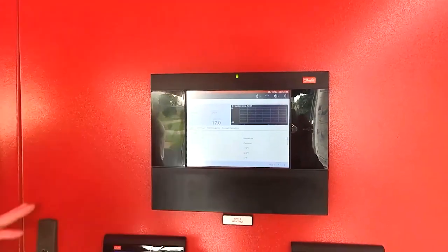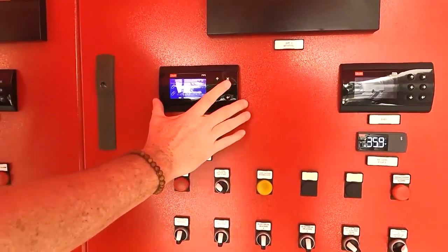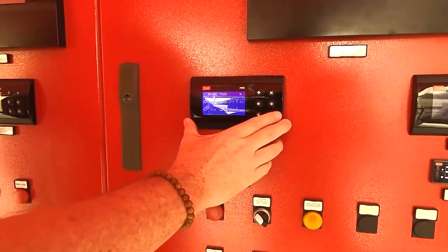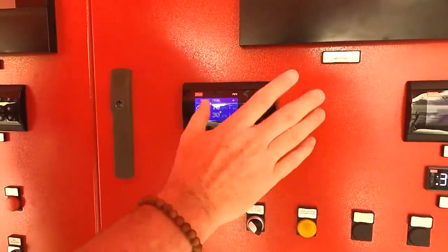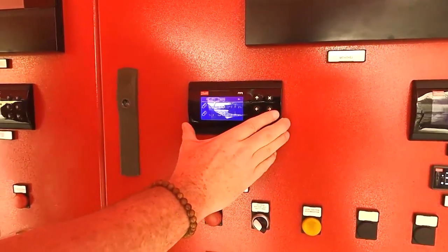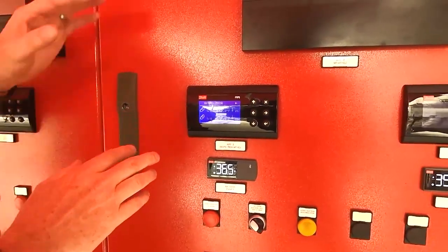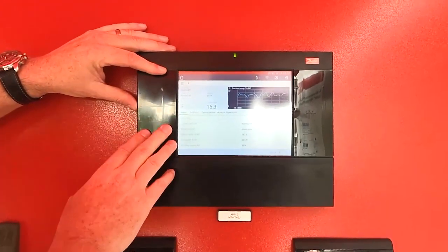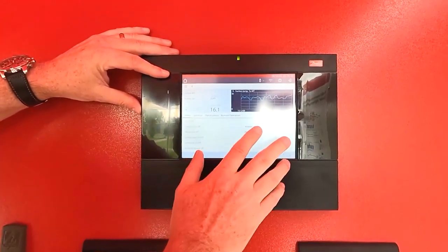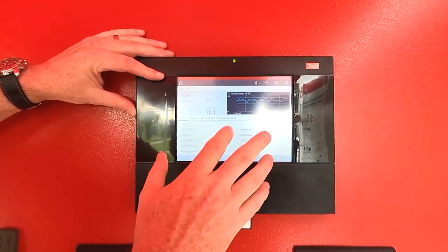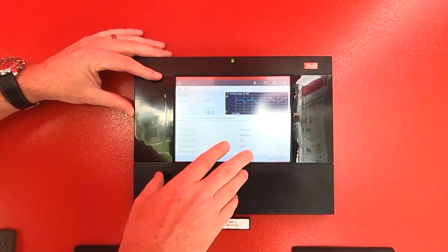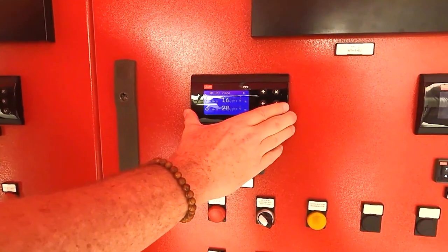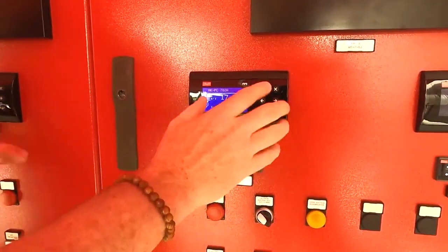There is also for the pack controller, if we come down one, there's also a remote display. We have a wonderful, easy to remember model number of MMIGRS2 for some reason. But this remote display will let you see the I/O for the pack controller. The system manager isn't meant for setup and configuration. It's meant for visibility and remote access to the pack controller. So you can't do anything with inputs and outputs here other than override some functions like compressors and fans and valve percentages. If you use our MMI remote display, it gives you full access to the pack controller, but it's a small display. It takes some getting used to.